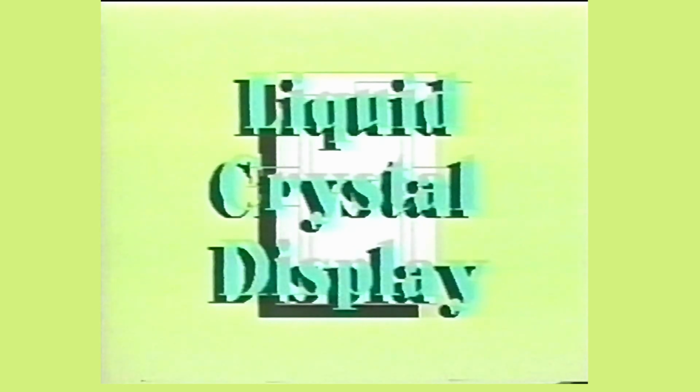The LCD, or liquid crystal display, is another popular 7-segment display device. Unlike the 7-segment LED display, the LCD segments do not generate light. Instead, they transmit or reflect light from external sources. As you shall see, there are 2 types of liquid crystal devices. These are the transmittive and reflective. Even though their operations are quite similar, there are major differences in their constructive techniques.